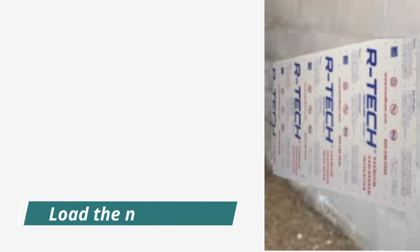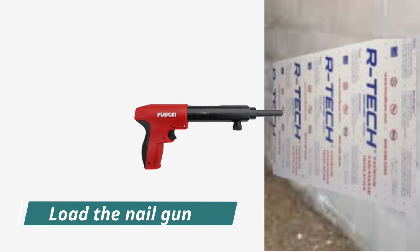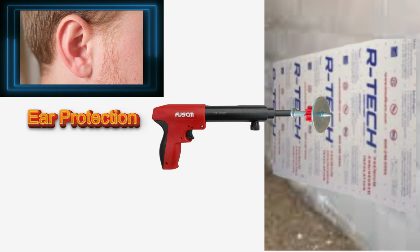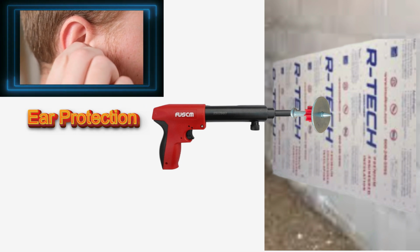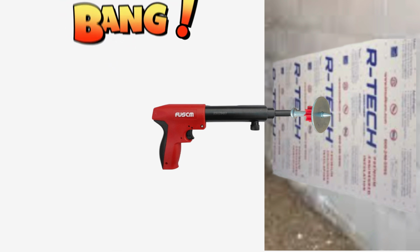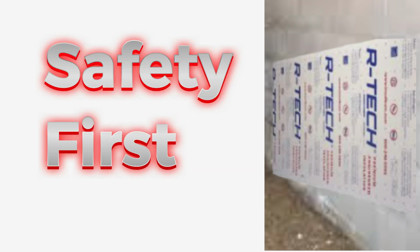Our final step in this process involves loading the nail gun with a bullet and nail, then pressing it against the foam board with it pressed tightly to the wall. I highly suggest wearing ear protection during this process. You need to keep in mind that you are going to get a loud bang, similar to firing a .22 caliber rifle, and nothing in your career is more important than keeping yourself safe.